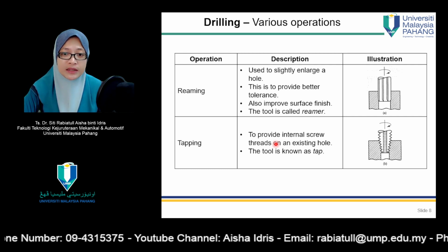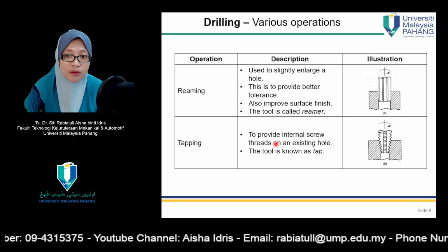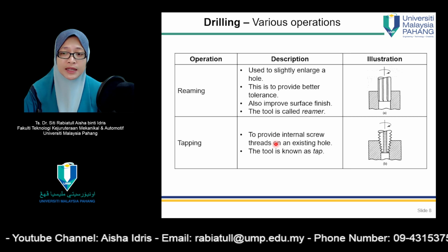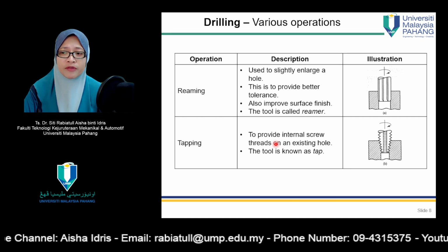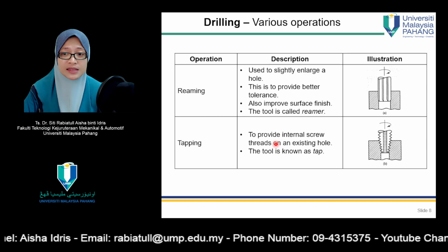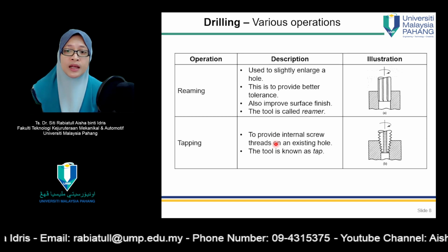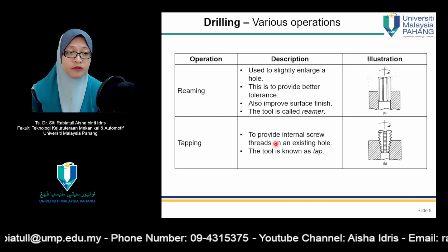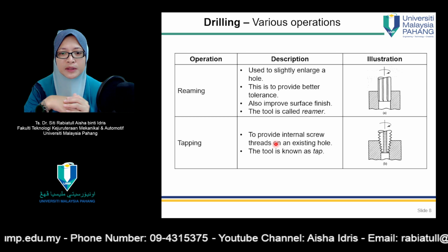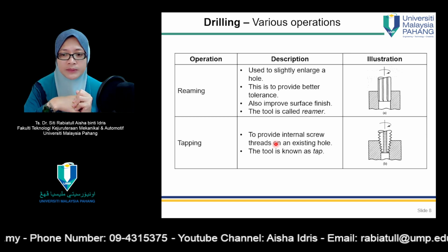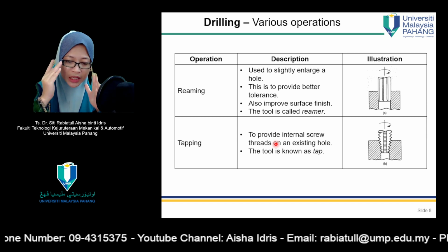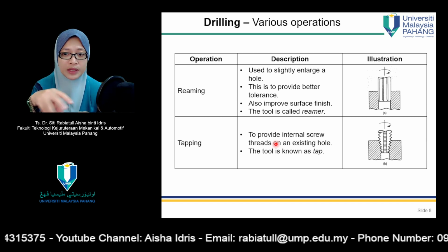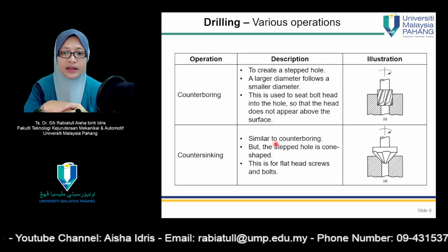So, you have seen in the video just now, there are various operations in drilling. For example, reaming. Reaming is a process of enlarging an existing hole, and normally it is used to provide a better tolerance or improve surface finish. Other than that, second is tapping. Tapping is a process whereby we have a hole, then we want to create a screw thread in it. So that is tapping.